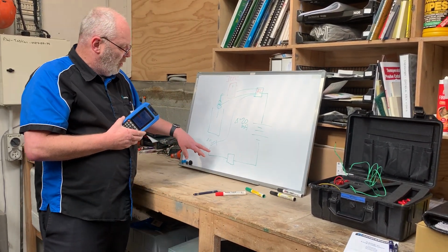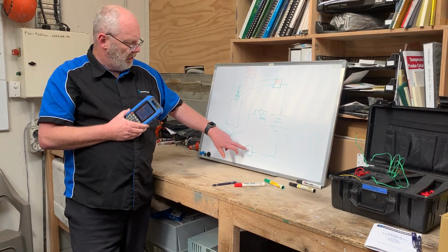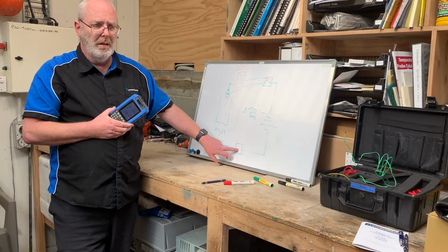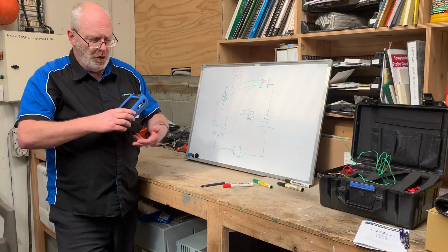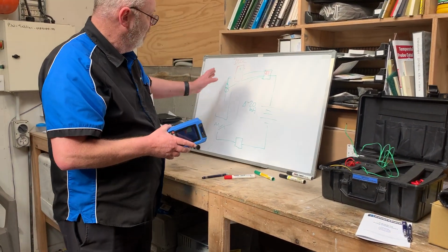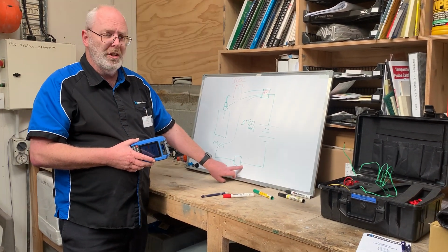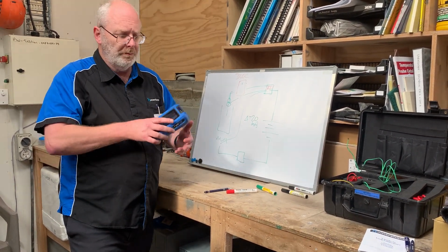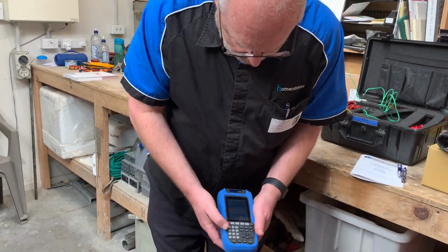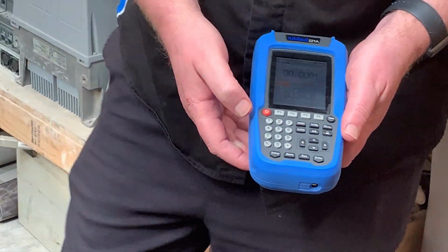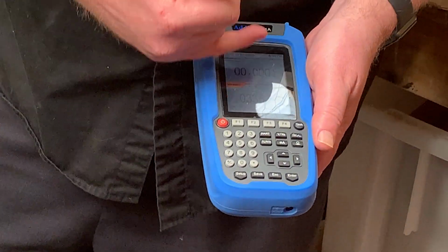So let's say you've determined that you think that this valve is not responding as you think it should. Instead of doing a thermocouple signal, testing the entire loop, you could have just a 4 to 20 milliamp signal injected in here. So if I exit that, remember source measure.